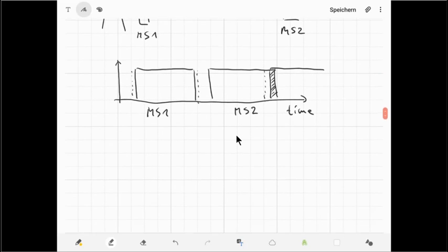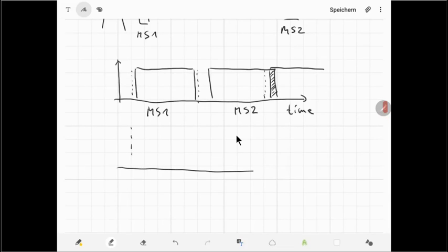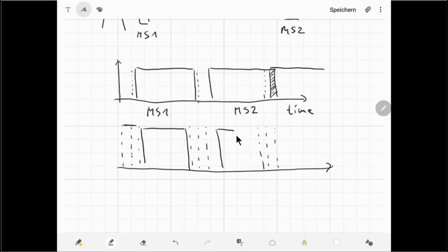And now we have the guard time, which is introduced here in the GSM-TDMA-frame. That means that if we look again in the timing diagram, we have again time slots, but around the times where the frames start and end we have so-called guard times. These guard times assure that if a package from a station farther away still transmits, it does not collide with the next package.